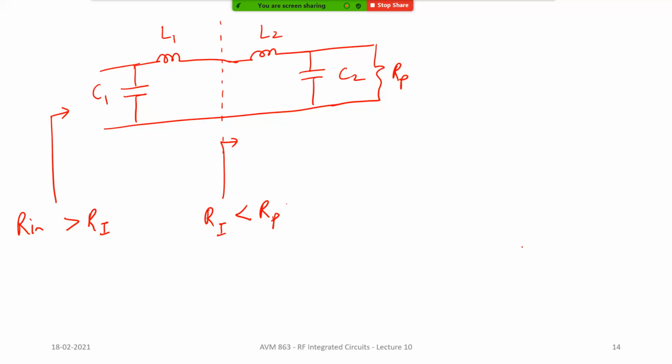Thankfully, in RF circuits, unless you are working with oscillators and things like that, the flicker noise does not directly affect you. Of course, in mixers especially, there is an up conversion of the flicker noise, so there you will have to optimize for flicker noise. So there is always a trade-off. That's how circuits are, or in general, that's how practical systems are.